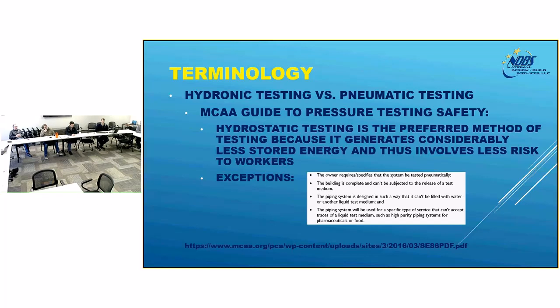You may have some owners that will require pneumatic test, although I have yet to find one. MCAA is kind of putting that in there to let themselves off the hook. If you have a renovation project that's occurring and you can't find a way to introduce or get rid of the water or the testing medium, then it's allowed by the MCAA.